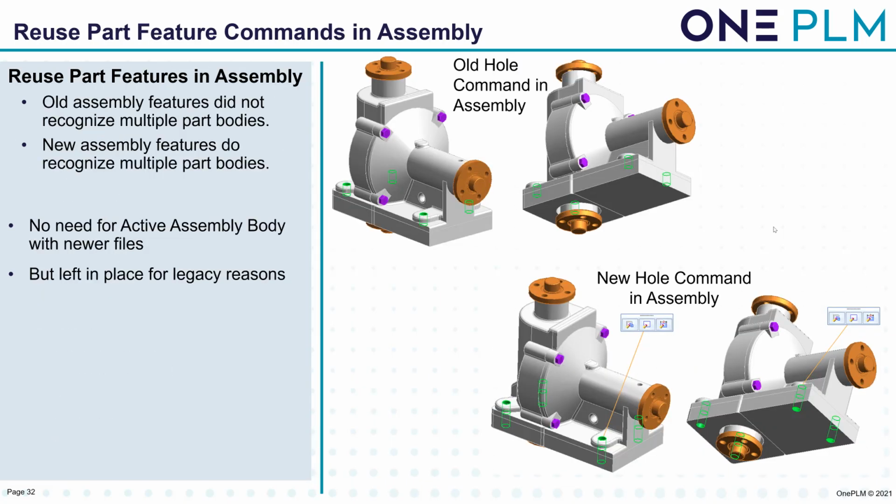So when you're doing a cut in multi-body, and you've got the little icon, two little rectangular icons split, dark blue on the top, light blue on the bottom, and there's two options, cut active body, cut both. That is now available in your assembly commands. So you can see before, we're just going through that first component with the 4 holes. Second, look at the 2 lower views, we can see that is going all the way through both of those bodies all at the same time.